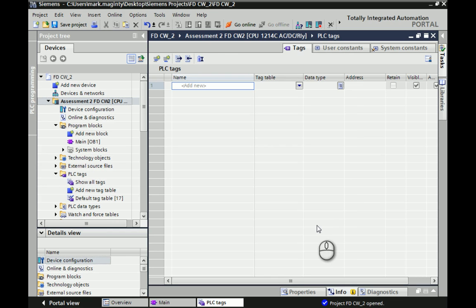Okay, so this is a video for recording, which is going to be a setup for the structure for the PLC program, coursework 2 for the PLCs course in the foundation degree. So folks, within this one, what we're looking to show you is the structure we're looking for you to obtain within the coursework. So we're looking to have OB1 set up, which is your organizational block 1.